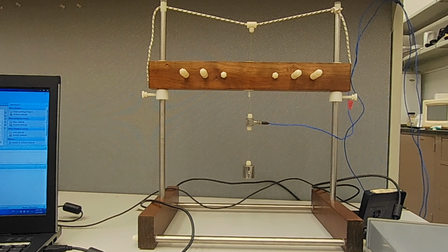Okay, so now we're going to look at gravimetric force calibration, because this time we have a load cell in front of us and we want to find out what the accurate value is for the sensitivity of this load cell. We have a known mass that is attached to the load cell via an auxiliary line. This mass is exactly 96.07 grams. And of course, the auxiliary line will have a mass of its own as well, but for the sake of this experiment, we can assume it's quite small.